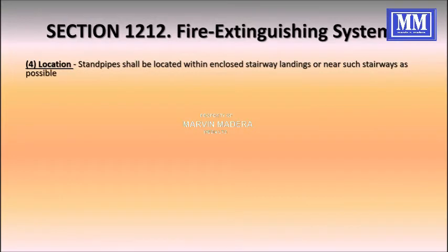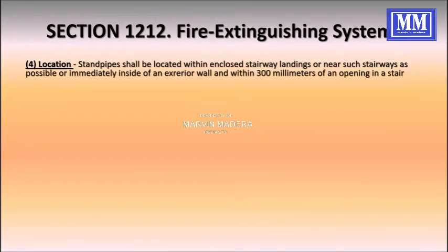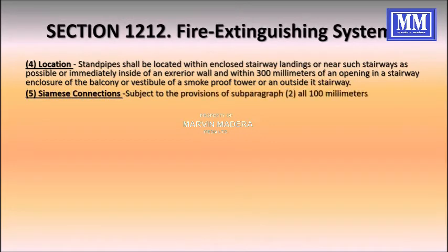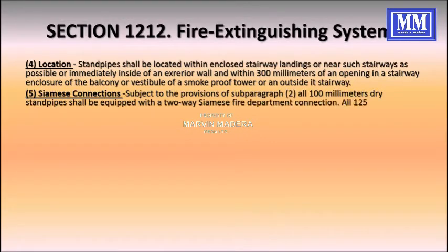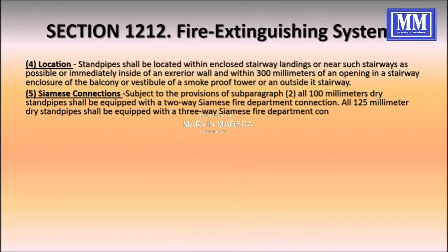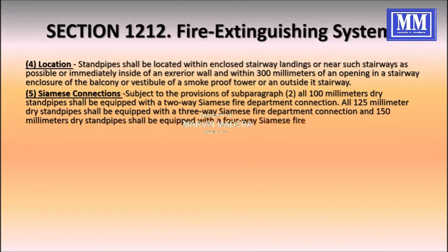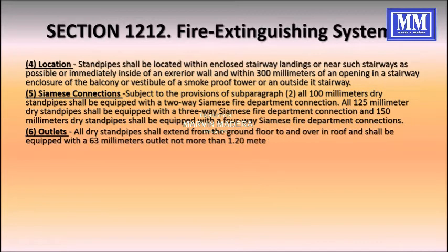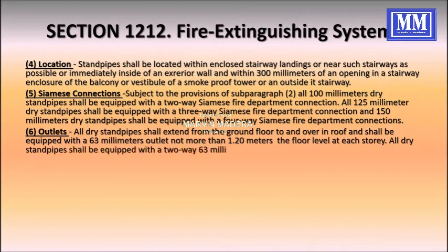Standpipes shall be located within an enclosed stairway landing or as near such stairway as possible, or immediately inside an exterior wall and within 300 millimeters of an opening in a stairway enclosure, of a balcony or vestibule, or of a smokeproof tower or an outside stairway.